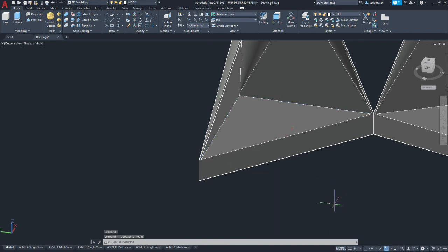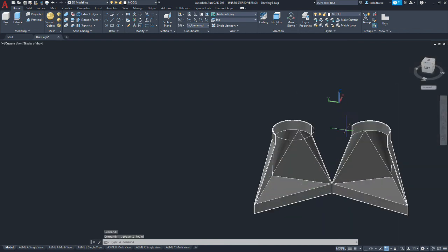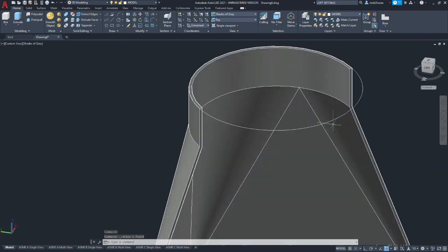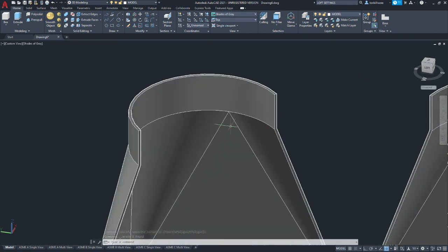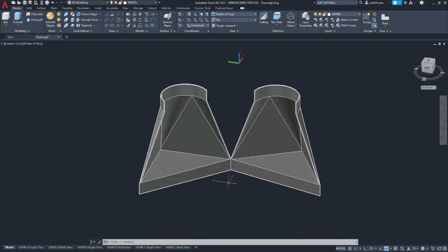Now if you want, you can get rid of that square I had there and the extra circle. We don't need this. Okay, so it should look something like this. It'll prove that you split it in half, that you've got the 1/8 inch in the middle, and that we have the correct faceting where you have the triangular flat broken up with the corner fillets. All right, that's it for this one.